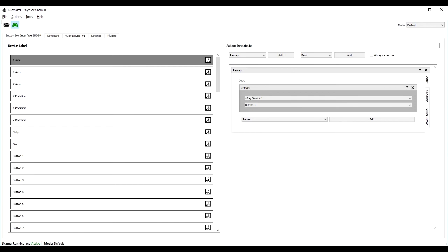With this software and vJoy, we can translate the on-off action on the LeoBodnar board into toggle or key press, exactly like when you press a key on the keyboard. We must use that with on-off switches. If not, your simulator will believe that you are continually pressing a key when your switch is in the on position and you are doing nothing when it goes to the off position.